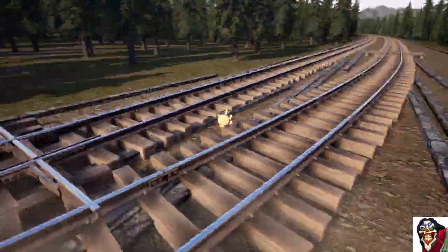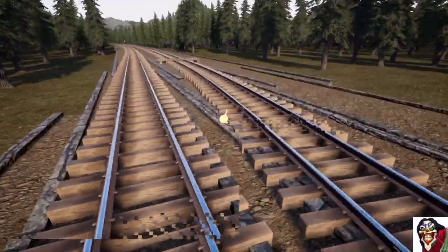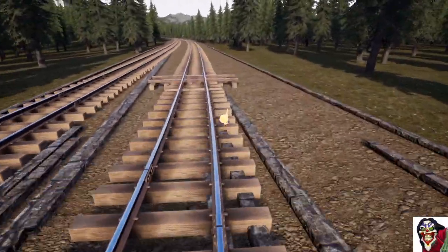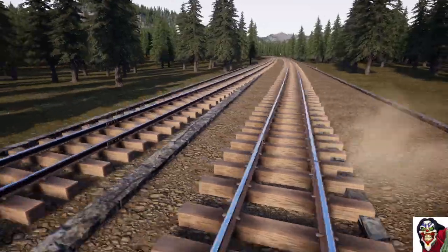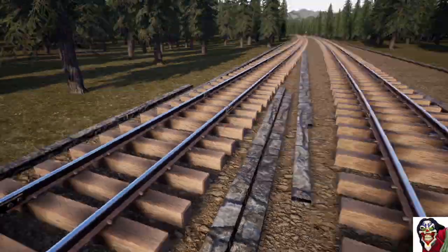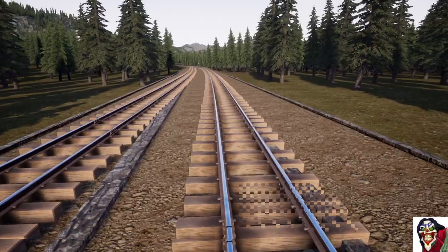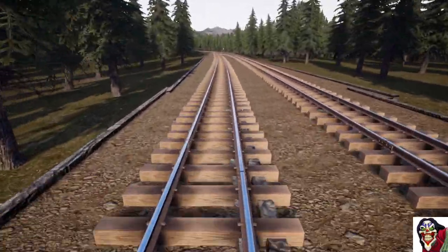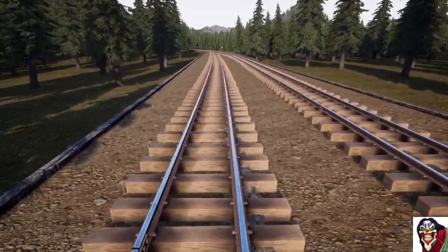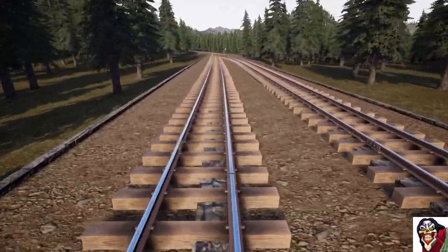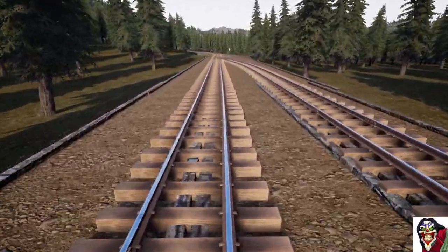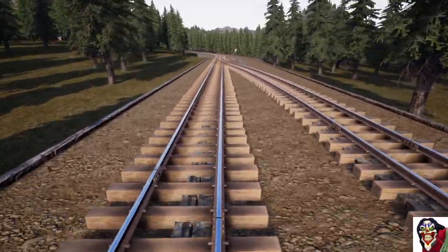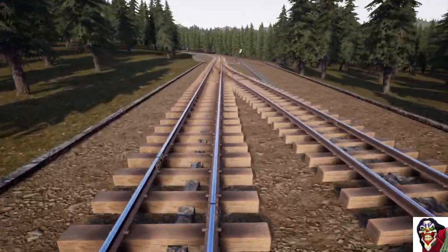We can delete the cross tracks we used to start off our splines. And there, all done. We have got a passing lane that is on a 1 degree curve on this side, and well, the curvature on this side is actually about 0.8. So yeah, you can't even use a 0.75 to try and put it in. It'll miss by about half a track's width over that length.